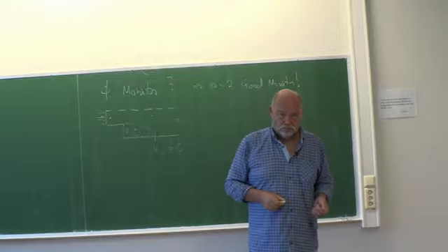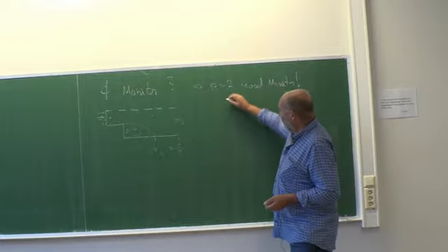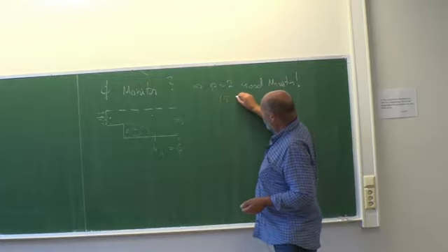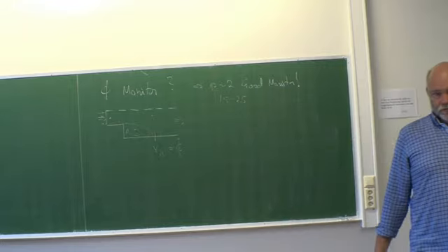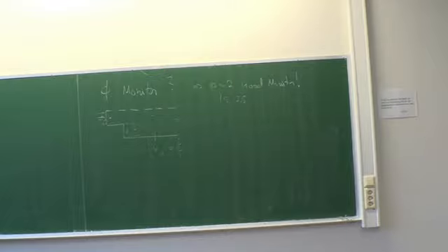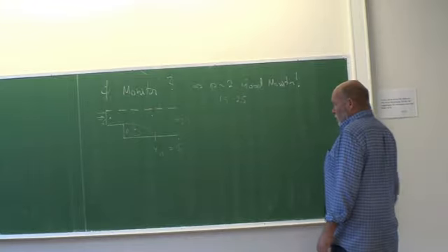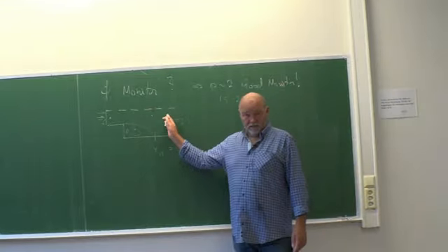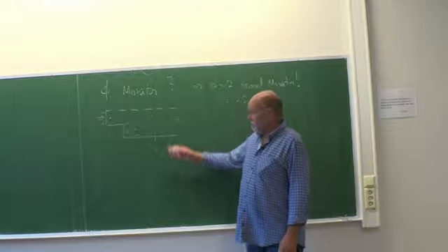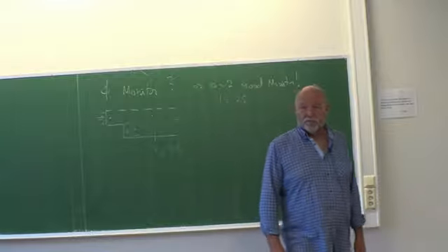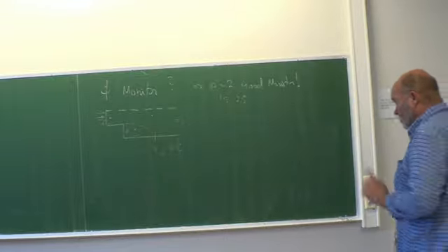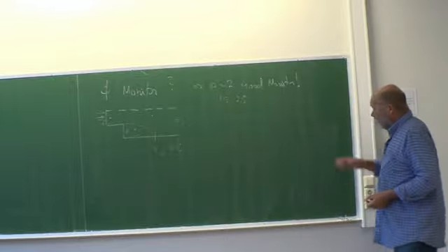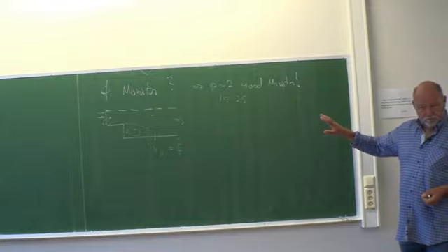I would accept 1.5 to 2.5, somewhere in that range. Then it's okay, and you can use that monitor and continue with the procedure. If you don't get it, try to find a better monitor. If you still don't get it, you have to create 3 different meshes. Maybe you have done something stupid with the meshes. So, tricky things. Any questions to that one?